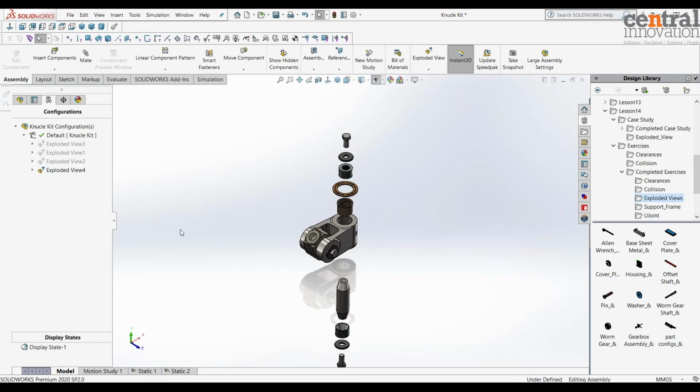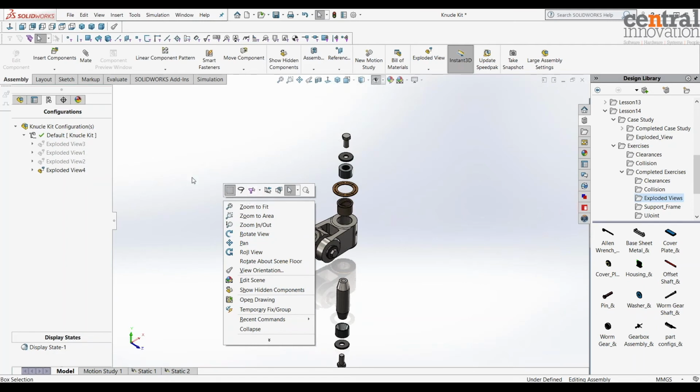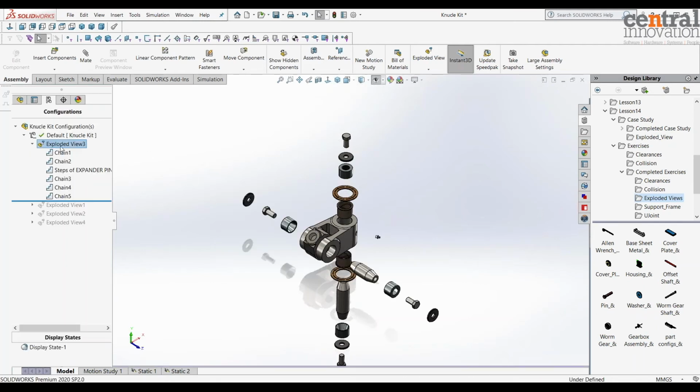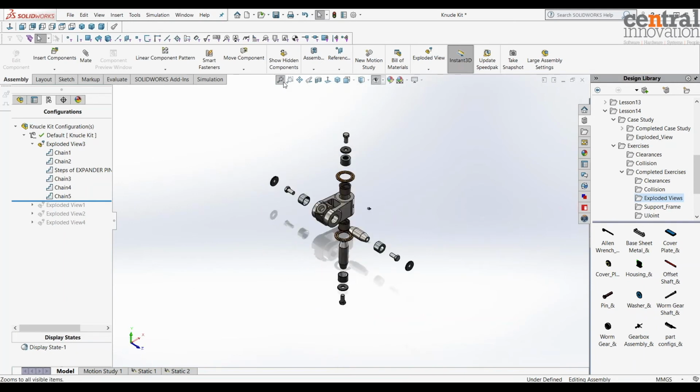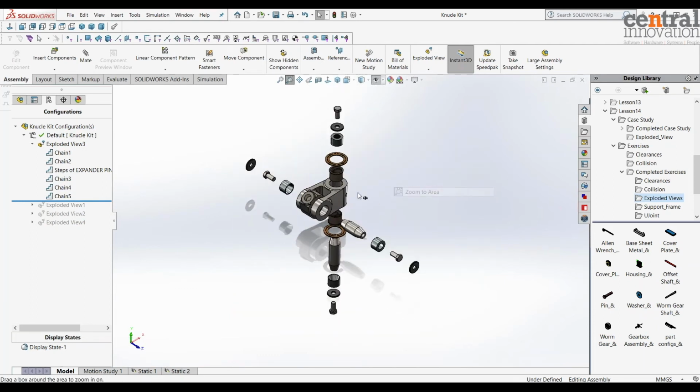So the purpose of this case study, to wrap it up, is that I'm not going to continue for the rest of the exploded view for this one, but I have created one before. I can show you. As you can see, I toggle between this sub-assembly, and this is the way that I have done my exploded view. So whenever you insert something from the toolbox, especially a sub-assembly into your assembly, make sure to check if there is an existing exploded view for that sub-assembly.